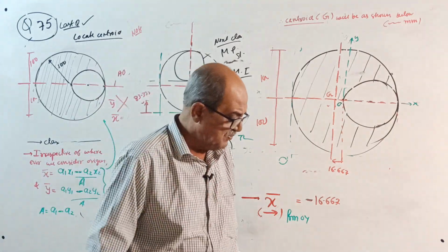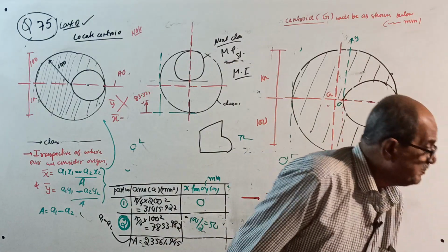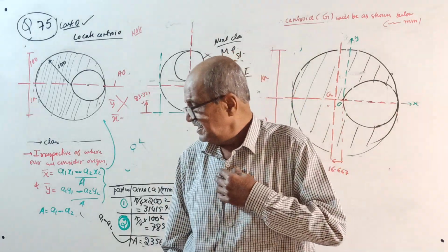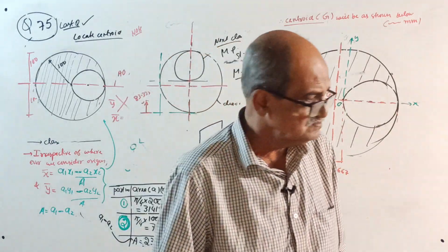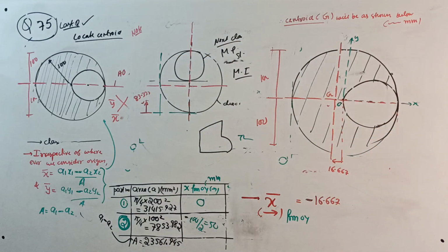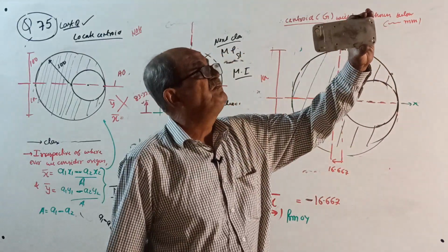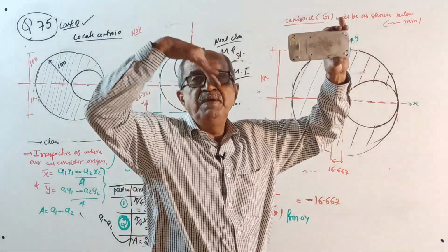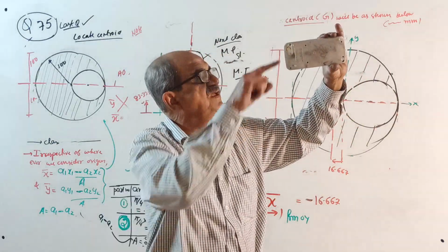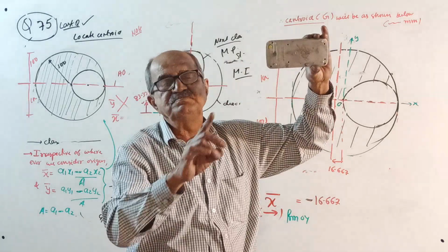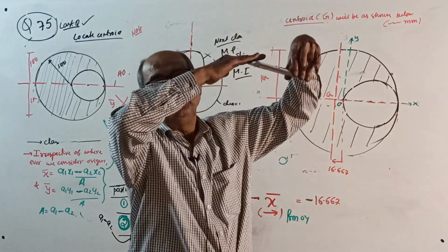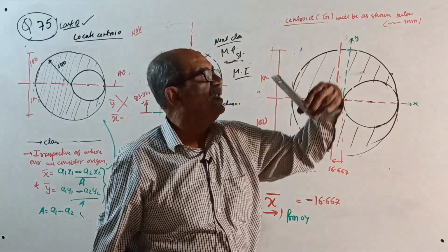See, I will give an example for you. Suppose there is a beam, just for information. You should start learning now. Some beam, rectangular shape. No, this is not rectangular, somewhat rectangular. Okay, I will use this calculator only. I use it as a beam bending this way. Moment of inertia is this into this cube by 12. If I turn the beam here, it will be this width into this thickness cube by 12.